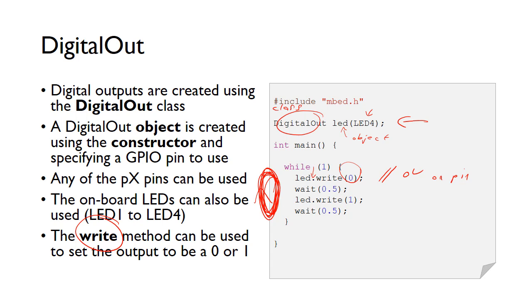Another function that's part of this Mbed API is the wait function. Wait, and in brackets 0.5, will tell it to wait 0.5 seconds. So the LED will switch off, we'll wait for 0.5 seconds, and then we'll do LED.write(1). That's going to put 3.3 volts on that pin, causing the LED to come on.